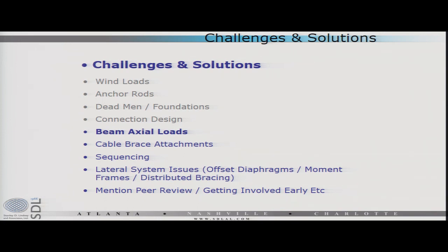The safety factor. Do we need a safety factor of 2? You need the same safety factor as you need for a permanent building. Why? Because ASCE 37 says so. But we have engineering judgment, right? Ah, engineering judgment, that wild animal that no one can find anymore. I am not going to stand here and say that I use less than the recommended safety factors for the design of temporary conditions. Yeah, but it's designed for 100 years, and you have 1 month. There should be a difference.